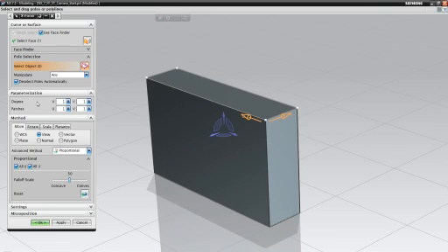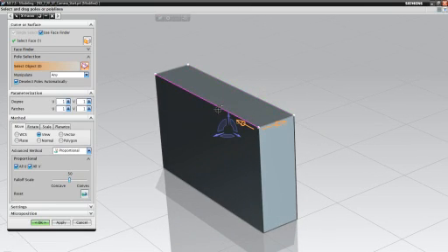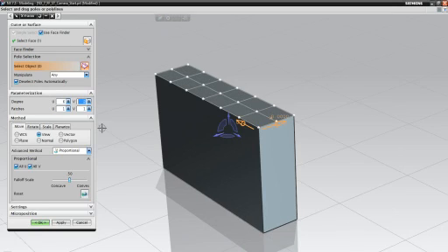So I'm going to select this top face to start modifying. How do I want to put these isoparameters in here so I can define this? Right now you see I have 4 lines and 4 points. Well, I want to up that a little bit. I want to add some more points so I have a little bit more control. Let's say add that in there.